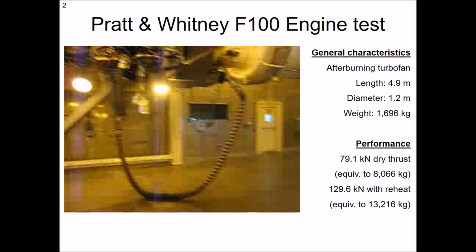This is an afterburning turbofan. When you see the scale of the power, it is quite surprising how small this thing is. It's only 5 meters long. It's only a 1.2 meter diameter on the intake. So most people wouldn't be able to stand in the intake. It's too small. It only, and I'm going to use the word only carefully, weighs about 1.7 metric tons. And if you look at the amount of thrust it gives for 1.7 metric tons, it's quite startling, the amount of power that comes out of it for its weight.